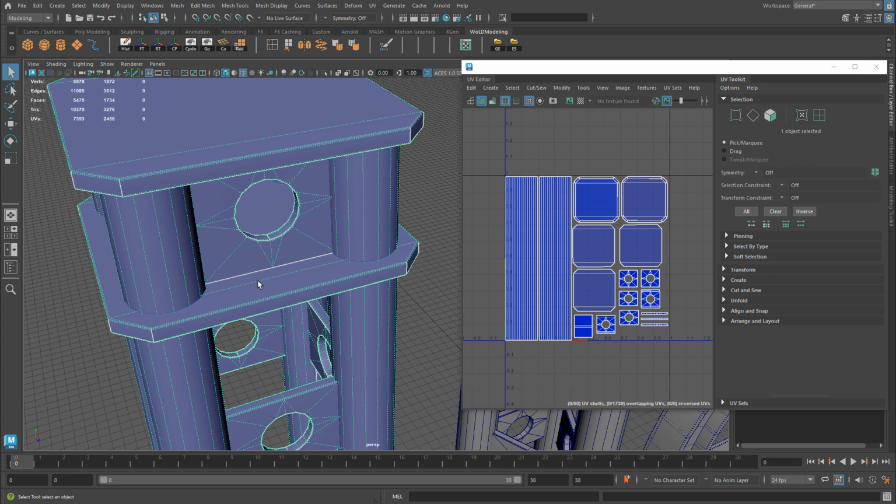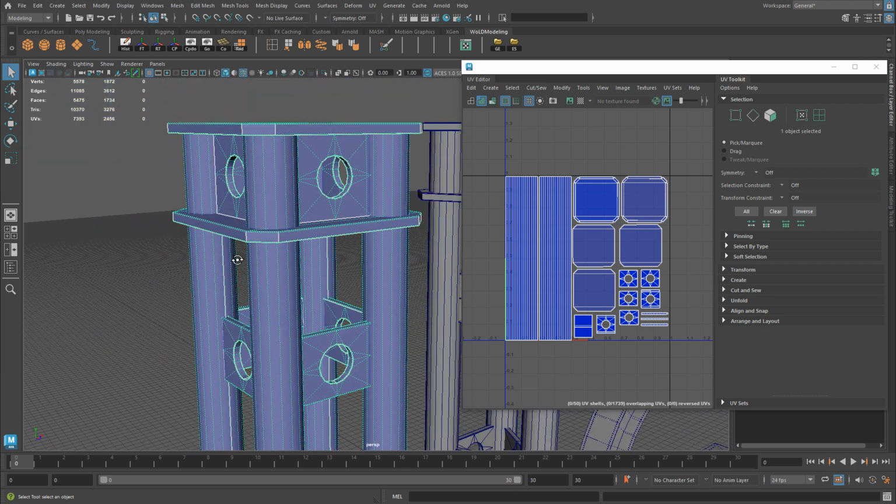So when I utilize that procedural dirt and dust generation, generally you do not want to overlap your UVs because some parts of the UV layout, some UV shells are going to repeat and not bake quite properly. You're going to have some inconsistencies and some errors in baking. However, if you know what you're doing and you know where these UV shells are, you could overlap some of them, and that baked info will be baked in for multiple UV shells, and it's not going to cause any errors if you know how to lay them out.